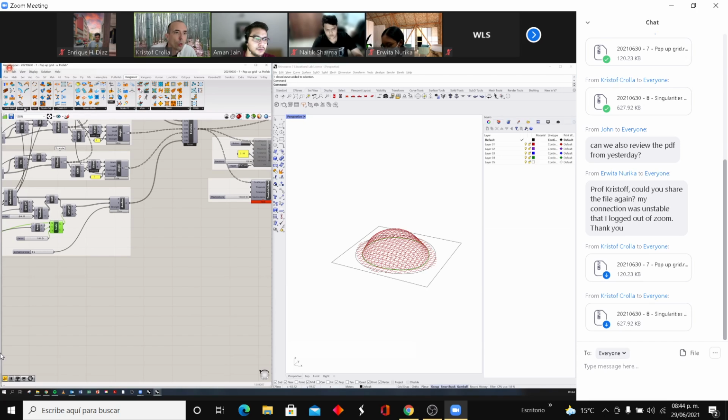There is a goal that you can have here to pull to a curve, I believe. And I forgot where that one is. But there are points on curves. I think it's goals over here. This one here: keep a point on a given curve. So that's basically like a sliding anchor. It's like you have a rail and all your points can slide along that one. That would probably be a better way to do that. And then you make it super tight, because then at least along the tangent vector of the curve itself, there's a degree of freedom. So at least there your points can be shuffled a little bit.